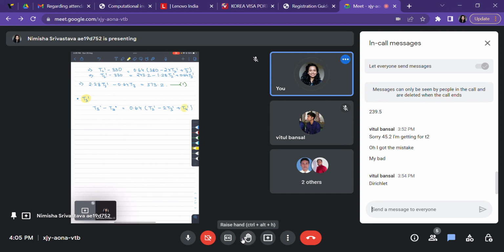Okay, which is this. This is a new one. This is unknown already. This is unknown. This is unknown. So I have another equation. Similarly, I'll write a similar equation for T41, and then in T41, what I get is T41 minus T40 equals 0.64 into T31, which is an unknown, T41 unknown, plus T51. So this is not unknown, this is a known. So here I can plug in my value. This is equal to 310 Kelvin.